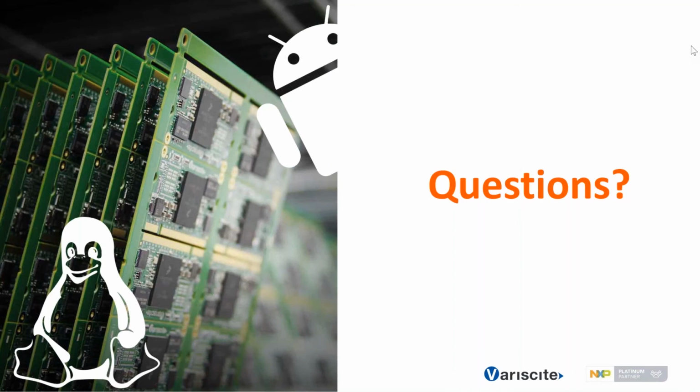It is possible to use all three. It all depends on the PinMux selection you're using. On our Symphony board, there's one compatible CAN interface. So it really depends. If you need all three, then you can define the PinMux to use all three, but then you have to see what you have to give up on in these pins.